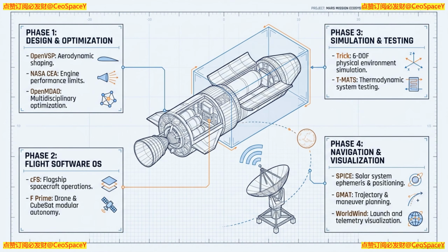Okay, let's actually define specific impulse really quickly, just for anyone listening who isn't a propulsion engineer. Good idea. The way I've always understood it, specific impulse is basically the miles per gallon metric, but for a rocket engine. That's a very solid way to look at it, yeah. It measures how efficiently you are converting your propellant into actual usable thrust, right? It's a measure of efficiency based on exhaust velocity. And the thing is, no matter how beautifully you design your engine bell or how incredibly advanced your turbopumps are, you can never, ever exceed the specific impulse limit that CEA calculates for your specific fuel mixture.